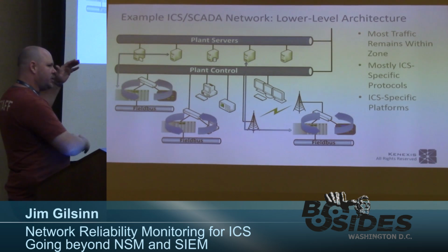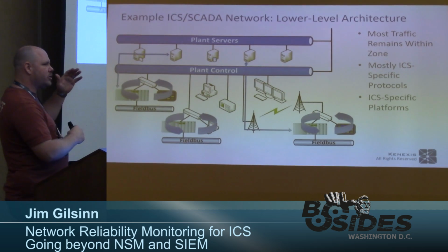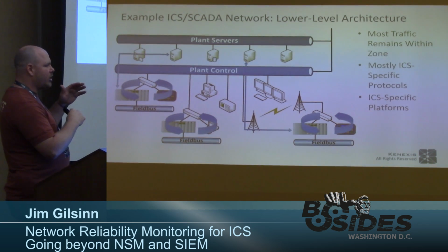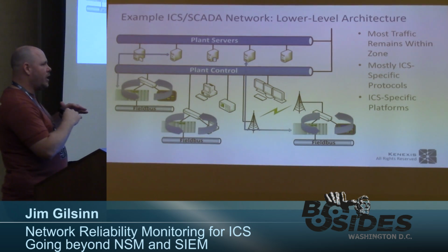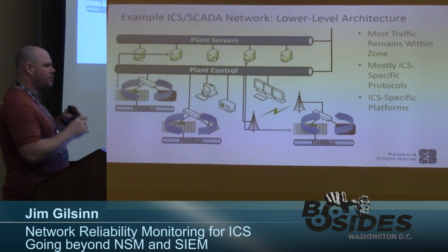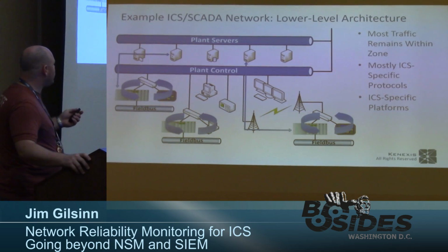Some of them use the full TCP stack. Some of them have found that they wanted to do more determinism, so they've actually eliminated portions. So some actually will reside right on top of 802.3. Some actually even get rid of the link layer in 802 and run right over the hardware layer of 802.1 or 802.3. So they get down into really trying to do sub-microsecond real-time communications with their systems.